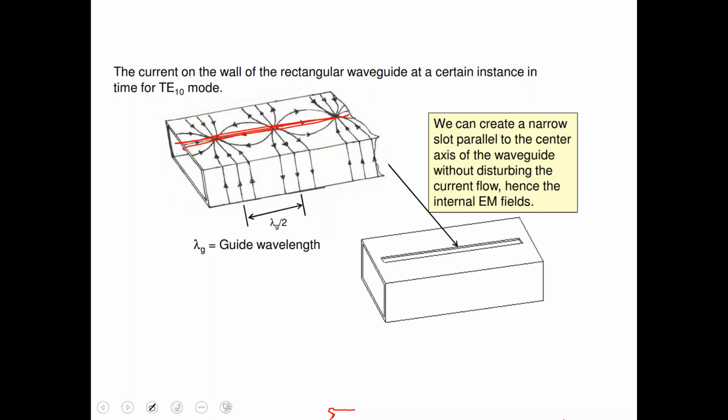This is called a slotted waveguide, and what this allows you to do is bring in probes, and you can now start putting probes inside through that slot, and you can start interacting with the electromagnetic wave which is going inside, either to measure it, or to capture energy out of it, or to be able to excite it.